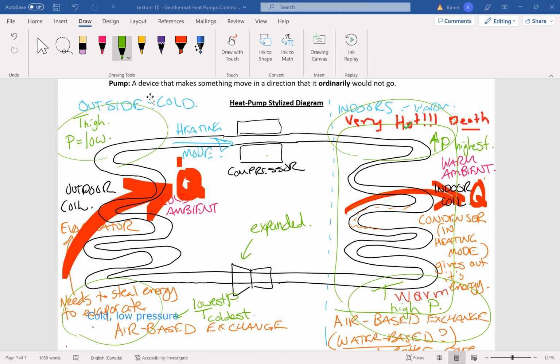Yeah, I have one question. So yes, we know that there's a valve that reverses the direction of the coolant, but a compressor will only still have one inlet and one outlet, right? You can't reverse the direction through the compressor. So there must be a valve that allows that change to happen too, right? Or am I wrong? Can you have bi-directional compressors? Does that exist? No, it's still going into the compressor the same way, and it's switching on the actual loop that goes into the compressor.